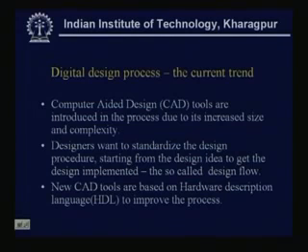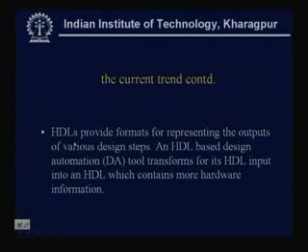So, some HDL languages have been proposed. Normally VHDL and Verilog are the different types of languages we use. Now, these HDLs provide formats for representing the outputs of various design steps. An HDL based design automation tool transforms its HDL input into an HDL output, which contains more hardware information.